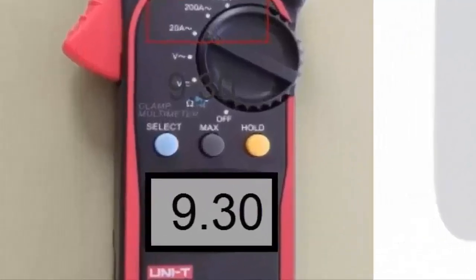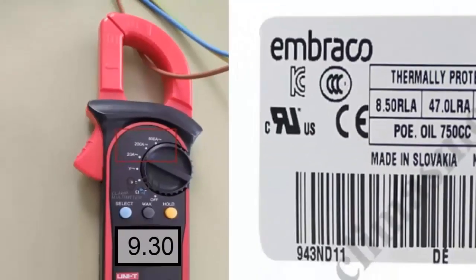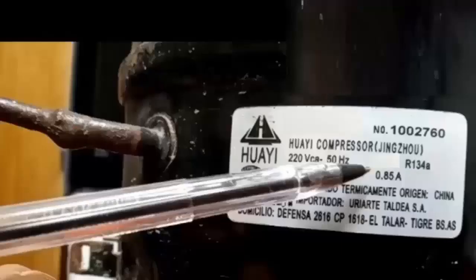Consequence 1. Excess refrigerant within a refrigeration or air conditioning system leads to electrical consumption above the regular consumption value, RLA, of the equipment, which can be easily measured using an amperemetric clamp and a power cable of the equipment.